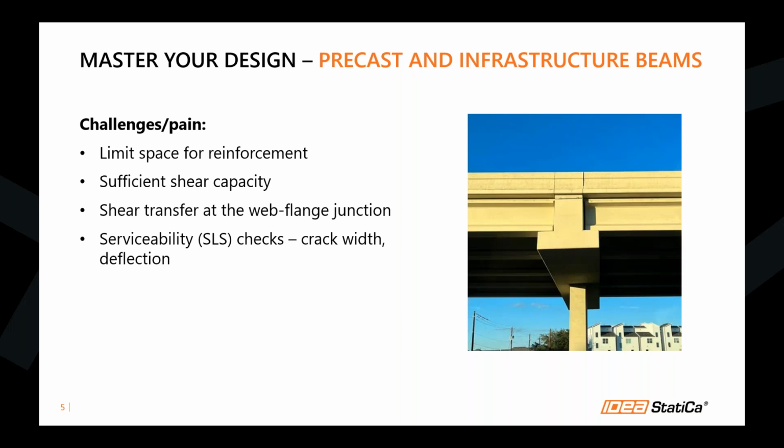For this beam, it's kind of specific that engineers must ensure sufficient shear capacity without over-designing the reinforcement due to the limited space for reinforcement. If we tend to over-design the reinforcement, then we would need to deal with congested reinforcement. So technically, we are limited by space for reinforcement.